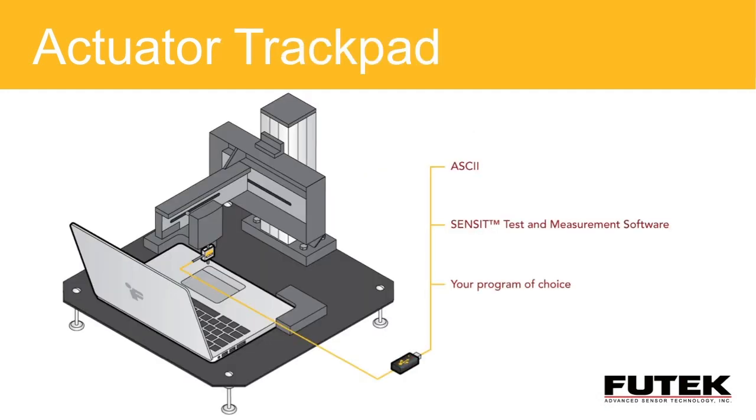So in this last application, we're actually testing a mouse touchpad. In this case, the force happens to be well within the 100-pound maximum of our LSB200, and the client has in fact selected that as their load cell of choice. So in this case, we're going from our LSB200 to our USB device. In this case, the customer is taking the USB information into their own control and providing their own programming solution.